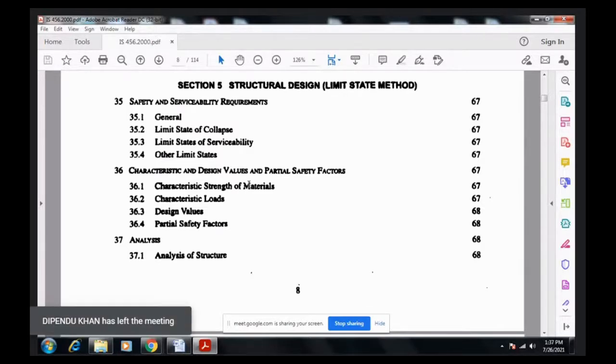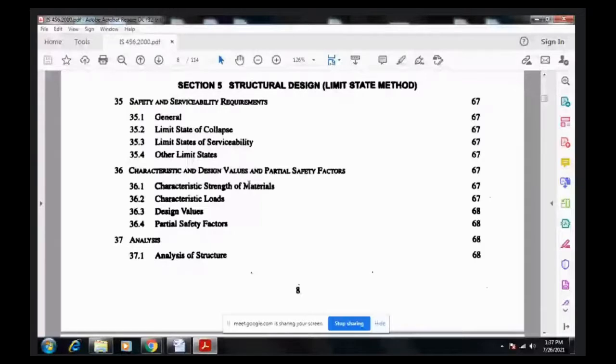But if you design it more or less elastic, behavior is more or less elastic, then it will be able to manage for 200 years, at least for the lifetime. So that elastic concept is definitely useful in machine foundations, whereas this is stress and release just throughout the day.